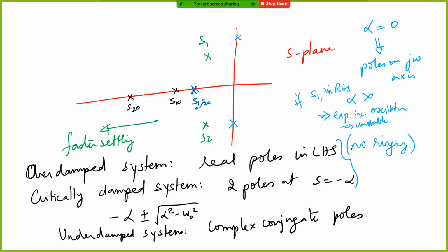I just want to make sure that you understand the relationship between the poles and zeros, which you find out in the S domain analysis, and the relationship with the time domain. This is very critical. Many students, and even professional engineers, struggle with this. What is the location of the poles and zeros, and how does it behave in the time domain? How does it behave in the frequency domain?